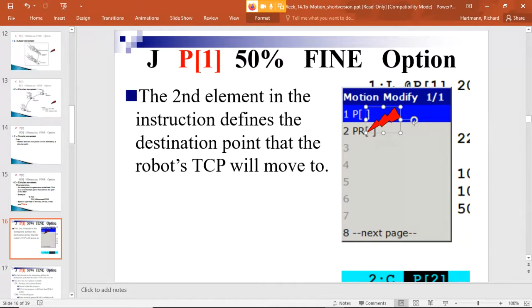There's 2 primary types of frames. There's the user frame and the tool frame. And we talked a little bit last week about the tool frames and setting them up using the Roboguide software. But when you then create these points, it stores that point in space based on your current frame of reference. Right? And so as long as you're both using the same frames, this position register is the same point in space no matter which program is referencing it. But a point is unique.